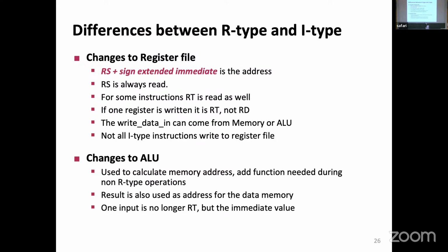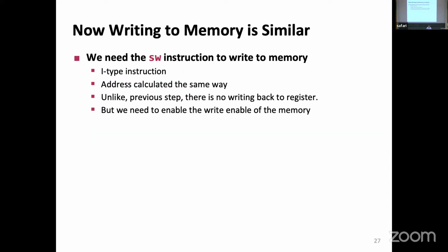And we make some changes, not in the ALU directly, but around the ALU. So we need to manipulate some of its inputs. The second input no longer comes only from the register file, but I put a multiplexer, saying sometimes you take it from there, sometimes you take this instruction's immediate, blow it up, and then send it to this thing. Let me hide this ugliness here, and we will see it in the slides in a few seconds.